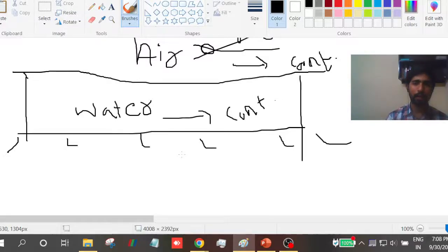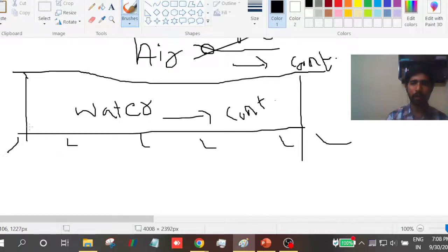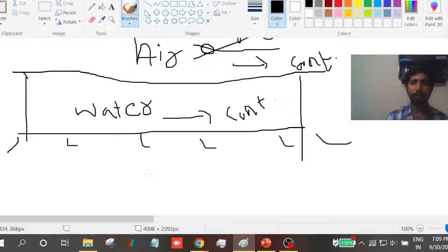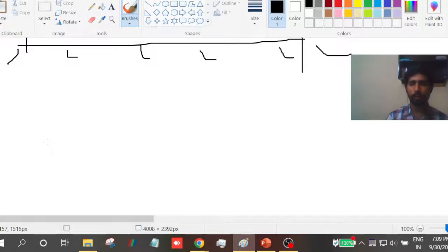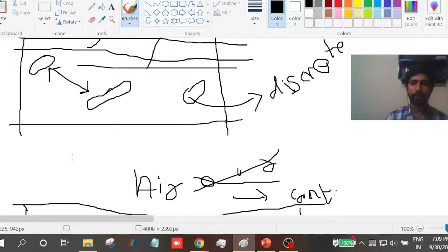Basically you have continuous phase and continuous discrete phase. Why we have to know this is that whenever we come up with a solution strategy, we have to understand the physics which is happening before actually developing a strategy. So for these set of problems, especially the continuous phase problem, maybe you will find out that one particular type of method, for example volume of fluid, may be a better method to solve. Whereas if you see the discrete continuous phase, you can see that there might be some other methods, like for example Euler methods, which we will discuss later. So those might be better to solve such kind of problems. So that is why you need to understand the physics which is happening. So that is why we discussed this in the beginning.